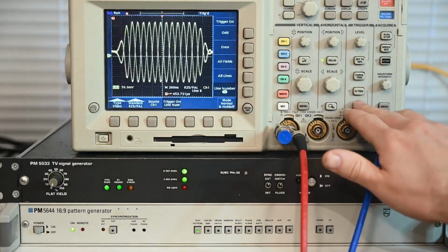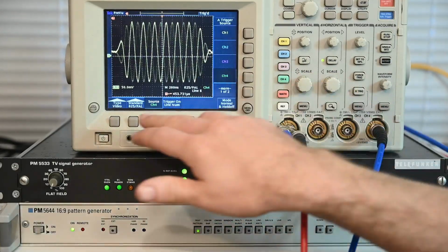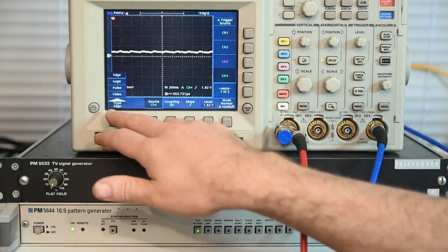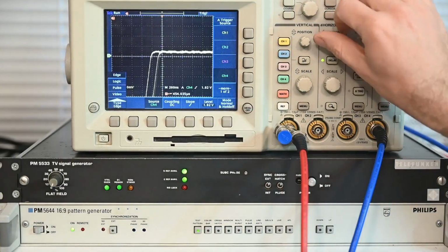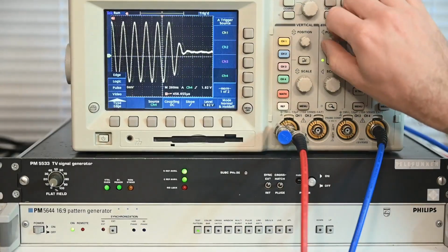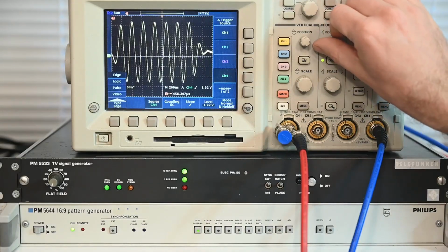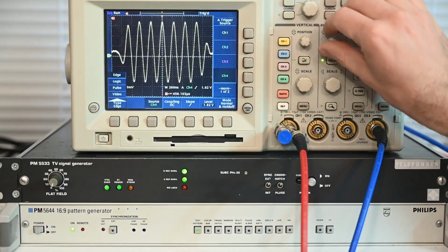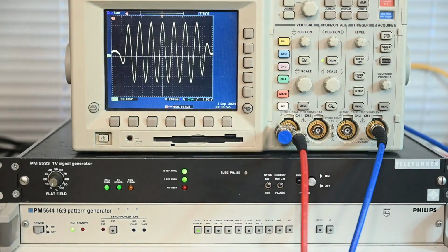That's going to be on channel 4. There's going to be an edge, and there it is right there. So there it is. As I say, this is quite a rare sight. That is the color subcarrier, or the color burst, in phase with the horizontal sync. Now this frame 1 sync signal is fairly infrequent, and it occurs at a frequency of 6.25 Hertz.